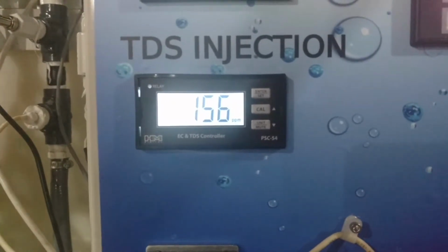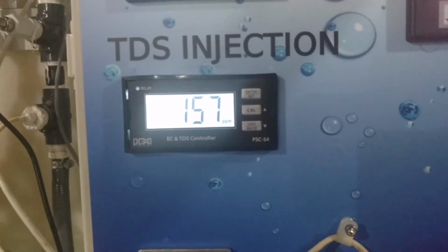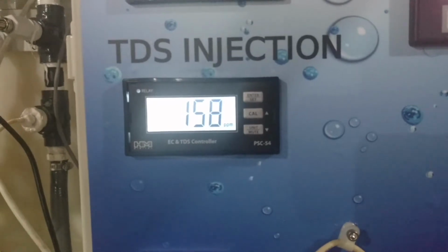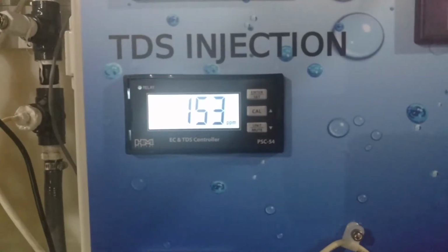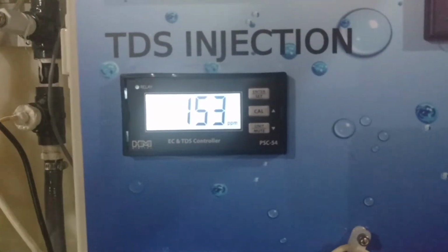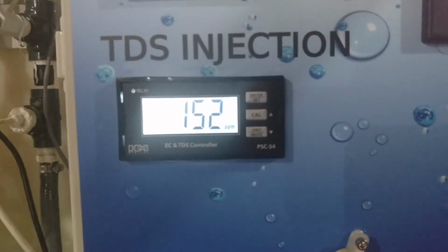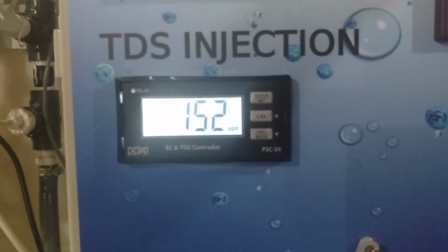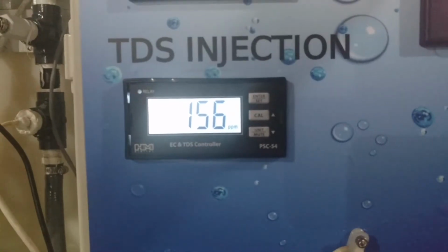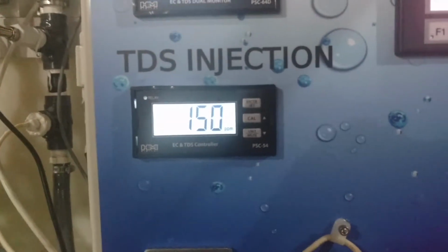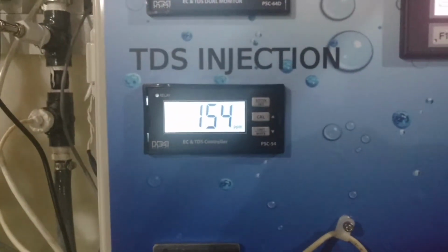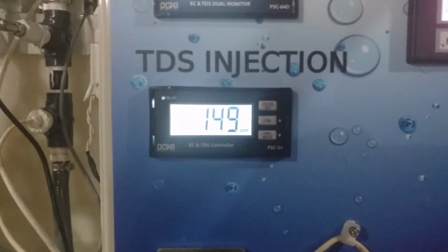We like to tell our clients that we can run plus or minus 10 TDS. After it starts trimming out, it'll usually drop to about plus or minus 5 TDS, as you can see here. The TDS you can change in real time, even as the machine is running, and I will demonstrate that now.